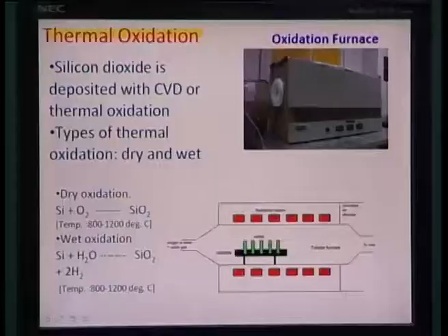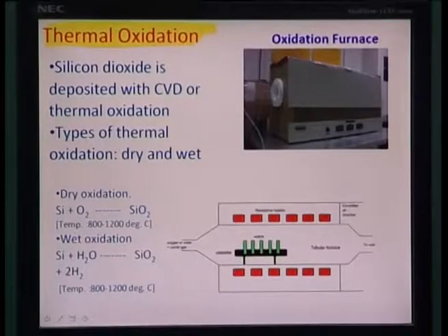So, let us look at some other microfabrication techniques. This, for instance, is thermal oxidation. It is basically used whenever you want to develop insulating oxide layers on top of silicon wafers, particularly to provide a proper insulated bed for electrode layout. For example, the interdigitated electrodes that you saw in the earlier sputtering example were made over a silicon dioxide surface which was thermally grown.